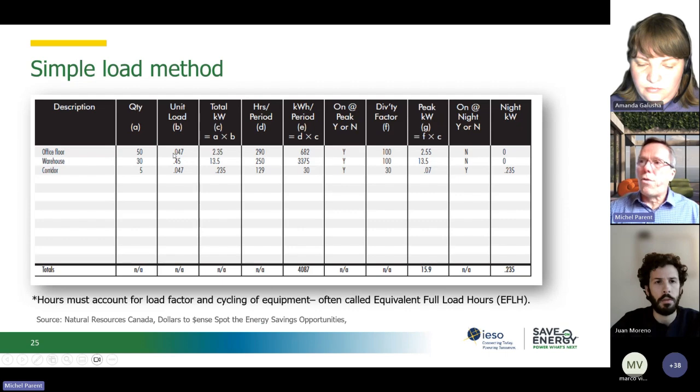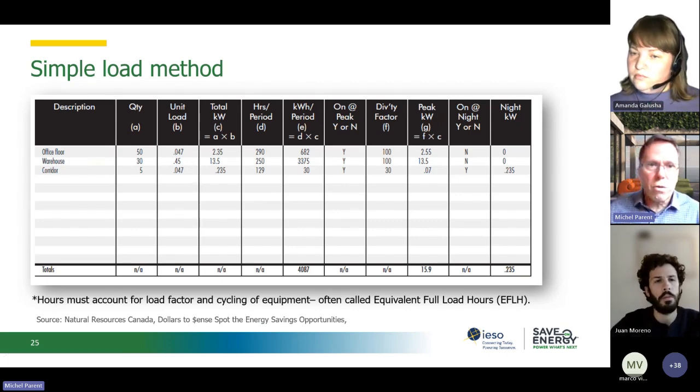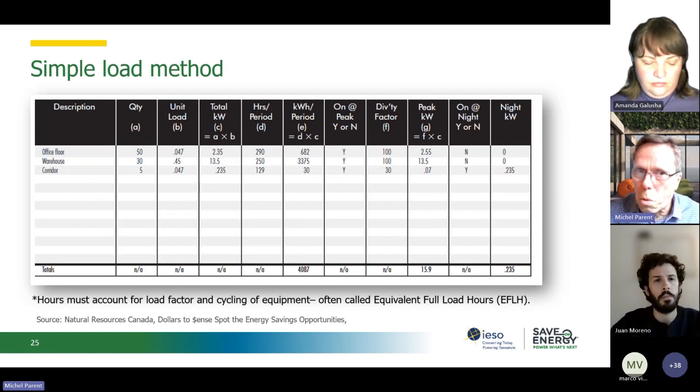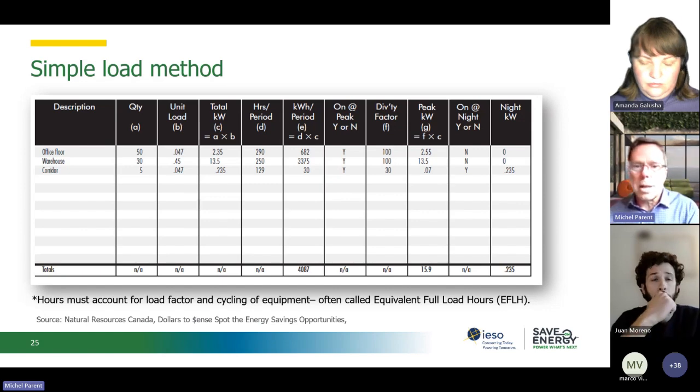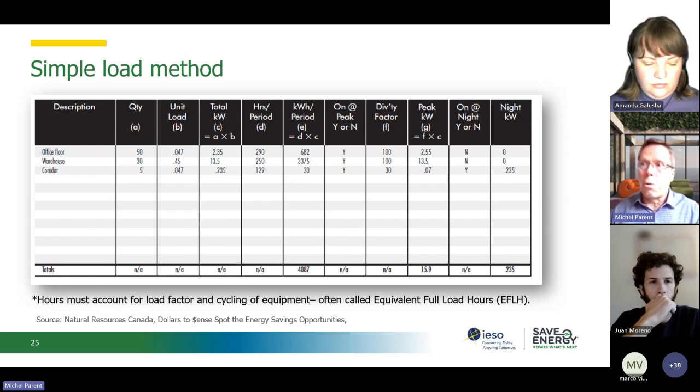And then if you've got, let's say, two T8 or 32 watts T8, that's old-fashioned fluorescent. Don't enter 64 watts here because your lamp is not drawing 64 watts. That's the nominal wattage of a fluorescent, but it has a ballast, which has a ballast factor. So what you will enter here is the actual drawn wattage by the equipment.